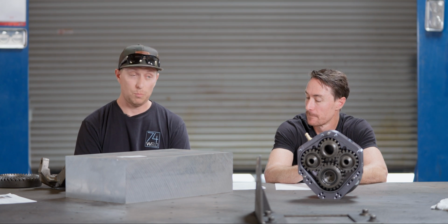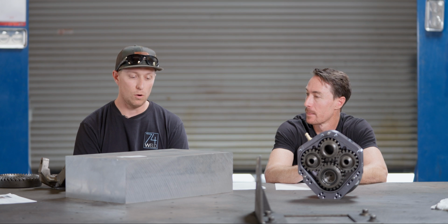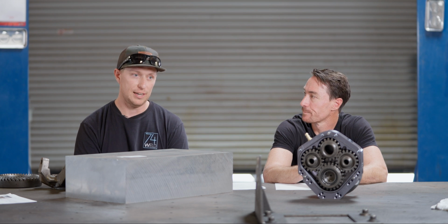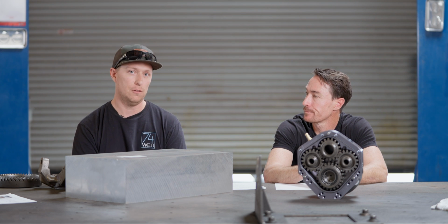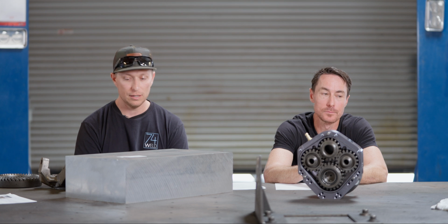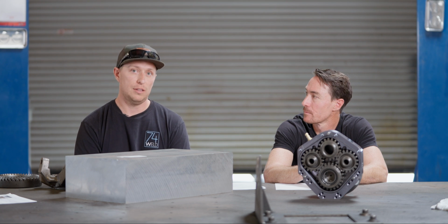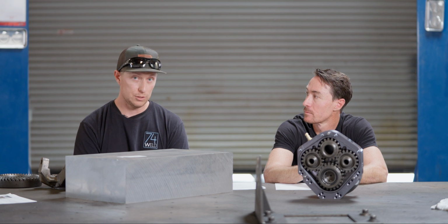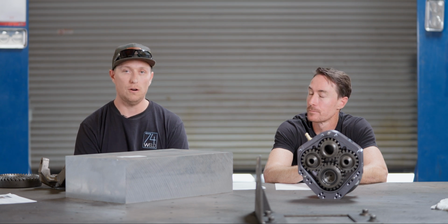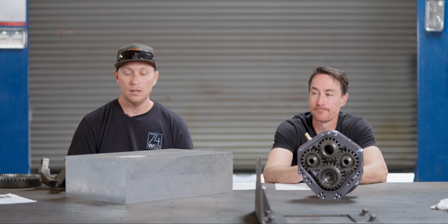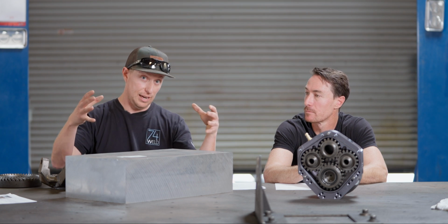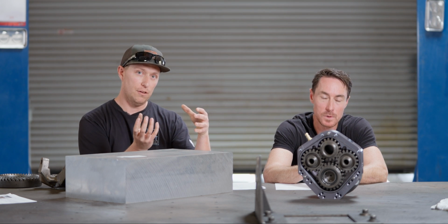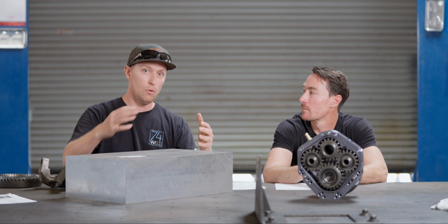Part of the reason why you want to use casting for a center section is all of the oil flow cavities inside of it. One thing you can do with casting is create what's called a core. Say you want a hollow center inside of a part, you can have this cavity in the sand and you can put a core in the middle of it, so now the material will flow all around it.